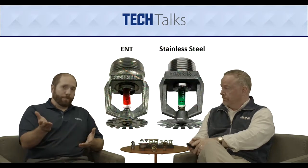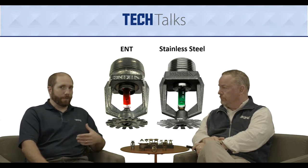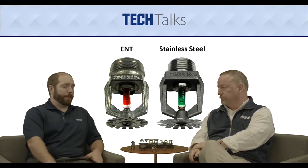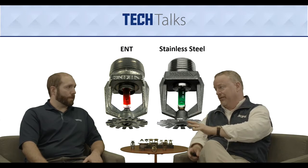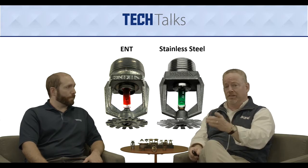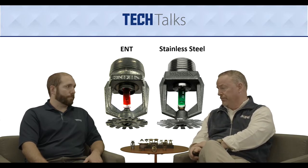Absolutely. ENT and stainless steel, right? Because they're going to be our more corrosion resistant type finishes, and they're going to completely coat or be the material of the sprinkler. So they're going to provide the best protection. For high challenge areas like that, if there's any question as to that atmosphere, then we're going to recommend at least ENT. And we'll come back to stainless steel a little bit later with a couple of other items where it might be best used.